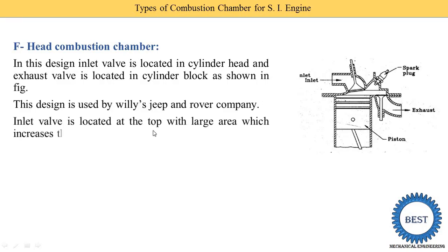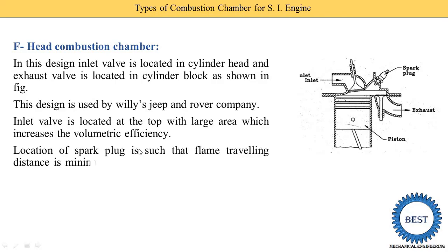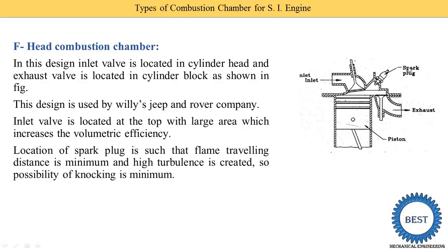The inlet valve is located at the top with large area, which increases the volumetric efficiency. So you see that this area is higher, so more quantity of the fresh charge is coming inside, so it increases the volumetric efficiency. The location of the spark plug is such that the flame traveling distance is minimum, and high turbulence is created, so the possibility of knocking is minimum.